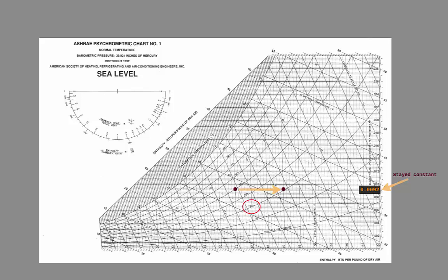Though the dew point is taken from the 100% relative humidity line, a quick investigation in the psychrometric chart provides that this value too is a measurement used to indicate the absolute amount of moisture in an air volume. Since relative humidity is dependent on temperature, it is usually better to measure for an absolute value of humidity, like that of humidity ratio or dew point temperature, when trying to control our humidity levels in an HVAC process.